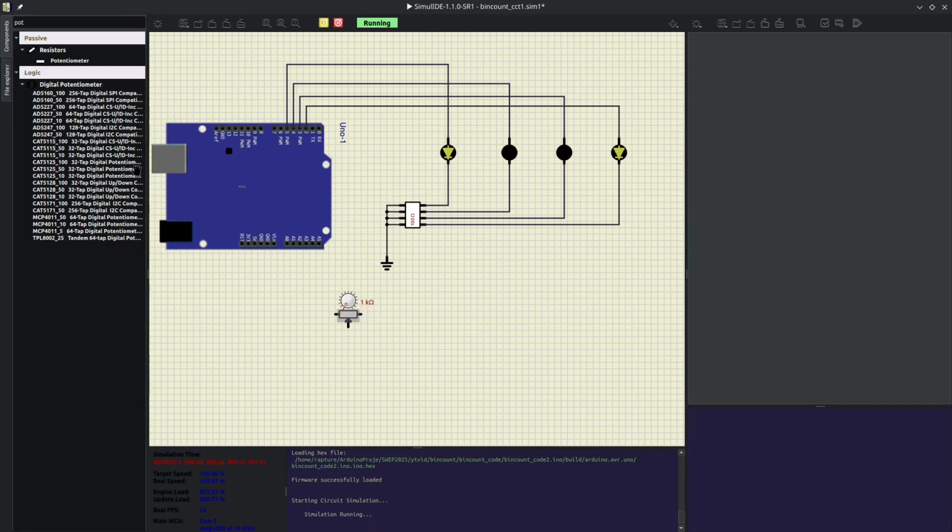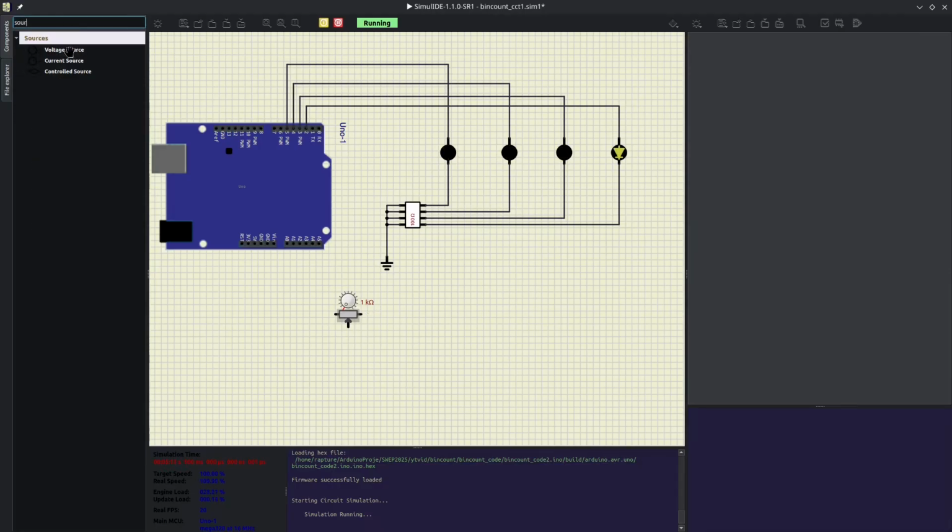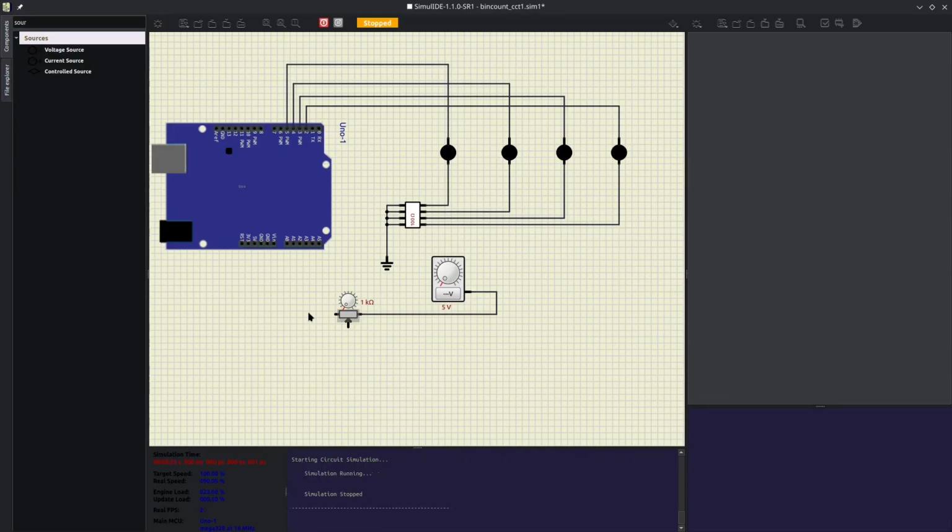We attach the VCC here. That means our fixed voltage will be, for example, our source voltage at 5 volts. You can also get your ground from the GND, or attach it to the ground here. The middle pin is where our data is going to go. The middle pin goes to A0. Then we are fine now.